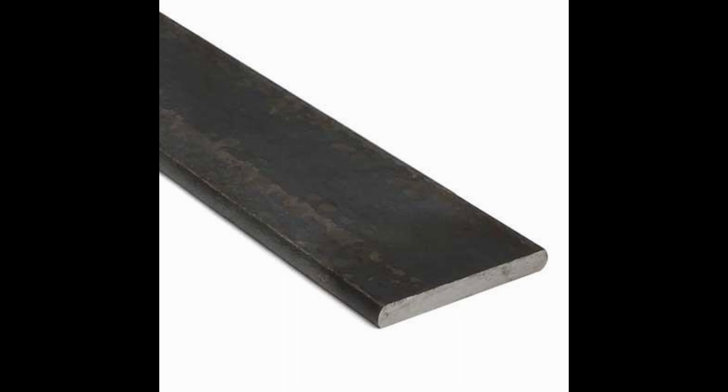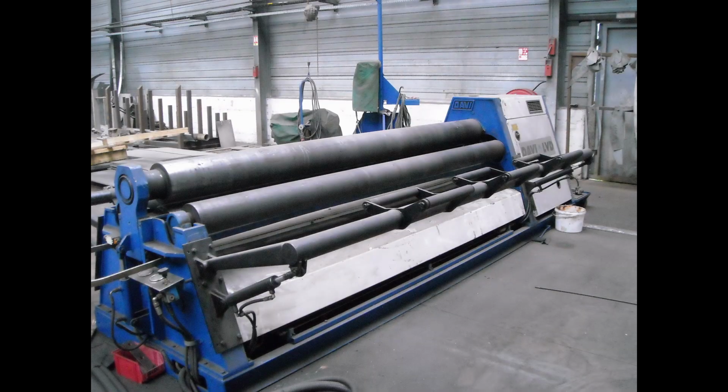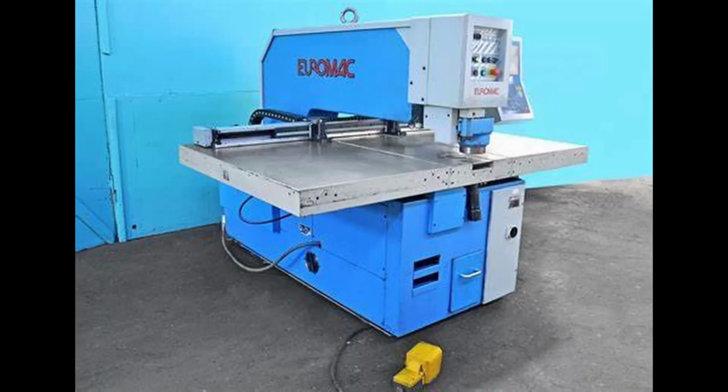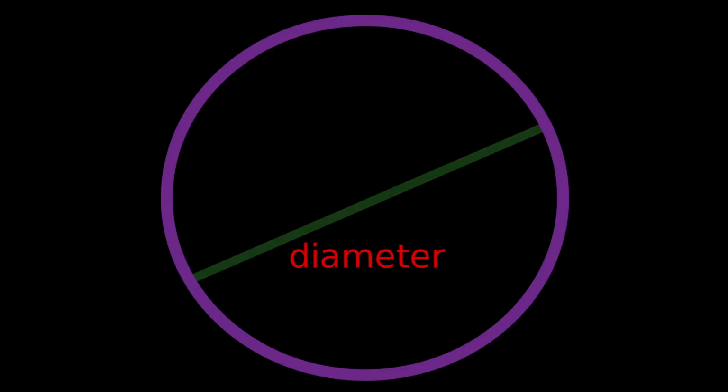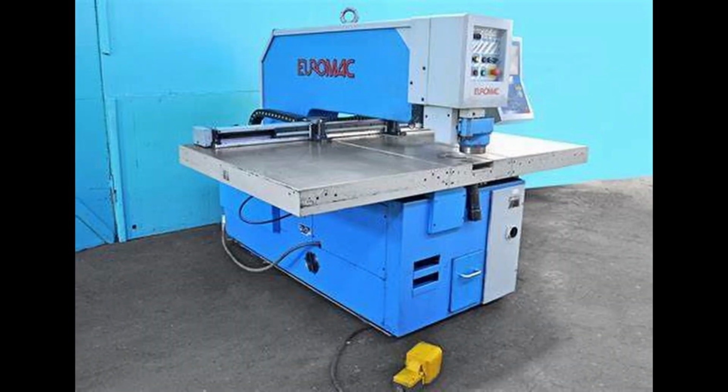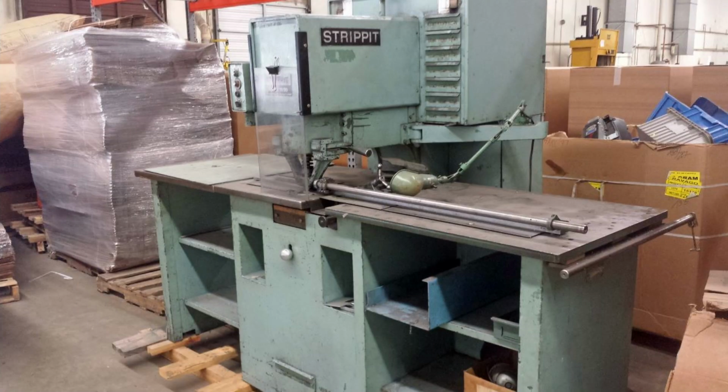Then we put our raw material, which is mild steel alloy, into the rolling machine to get the thickness as required for the washer thickness. We move on to the punching die and set the punching die as per the required internal and external diameter of the washer. After setting up the punching die, we then feed the mild steel alloy sheet into the punching machine. As per the number of dies per stock, an equal number of washers will be produced.